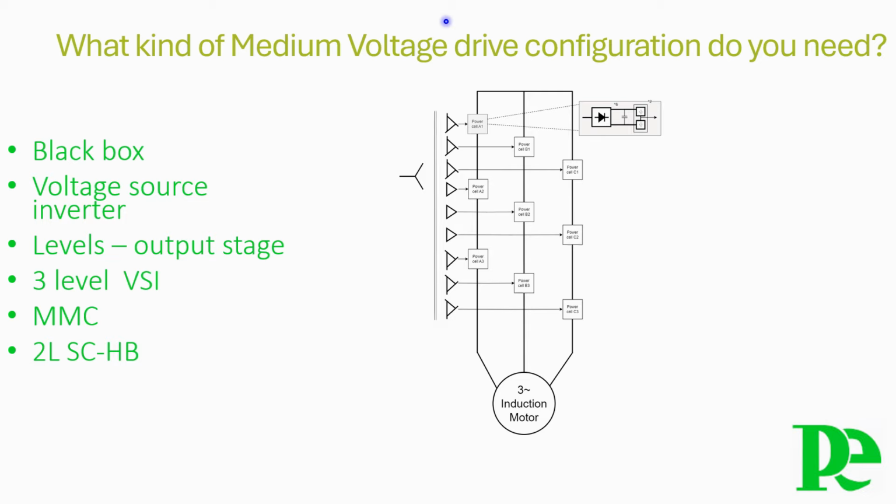The result of adding up the output of multiple low voltage power cells is a high quality output voltage providing less than 1% induced torque ripple, no need for an output filter for motor cable lengths even up to 2 km, a high reduction in common mode voltage, no derating on new or existing motors, no voltage spikes at the motor thanks to small output voltage steps, thereby allowing the use or the reuse of a motor with standard insulation, ideal for retrofit.